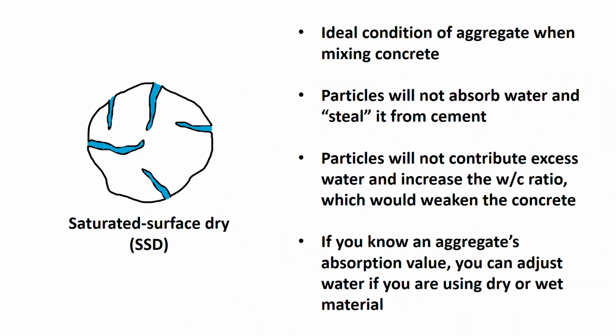I can't go back to the prior screen, but that was just a screen that showed the different moisture conditions of the aggregate particles from dry to wet. We have to account for the moisture conditions of the materials that are being used, and those moisture conditions were given in the material specifications at the very beginning. So we will need to adjust those final mix design weights that we just looked at.